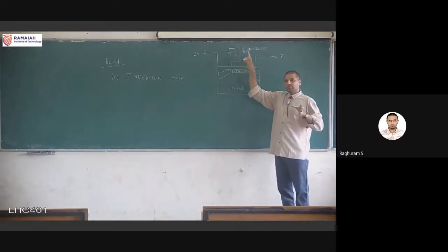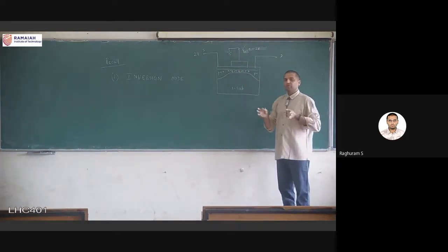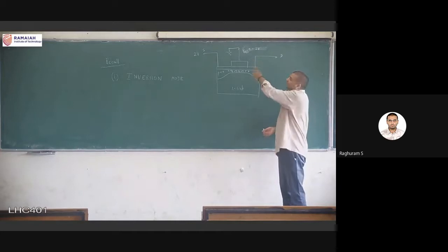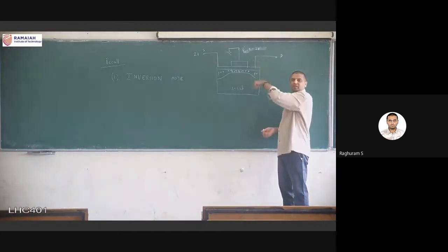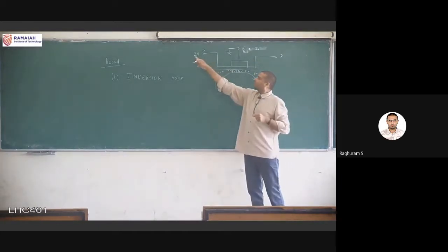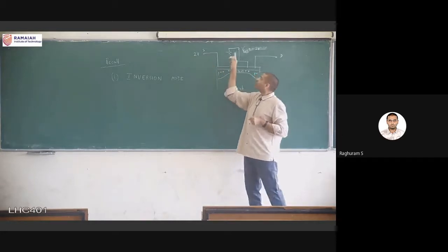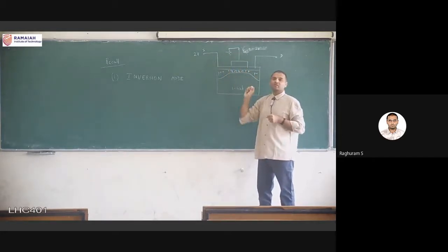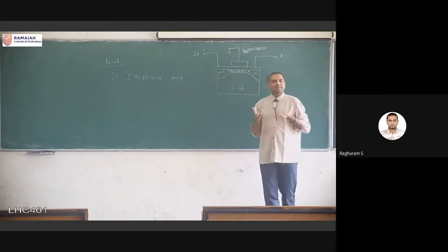Like we've been saying, we don't have negative voltages as such, but relatively, with respect to one another, we can get -2 volts. This is how we get that: connect the gate to ground, and connect the source to 2 volts. So what is VGS? It is VG minus VS, or 0 minus 2, which is -2 volts. And -2 is a nice negative voltage.